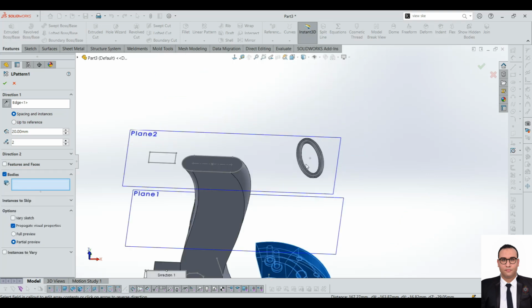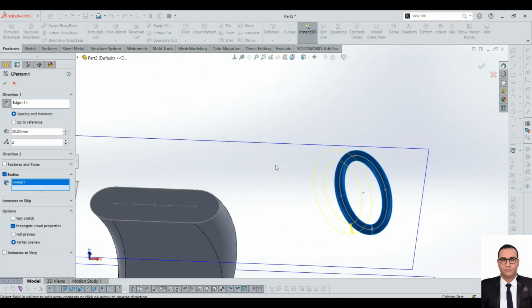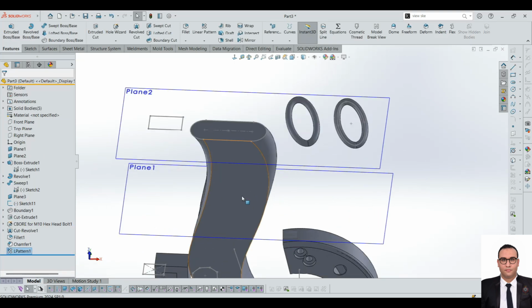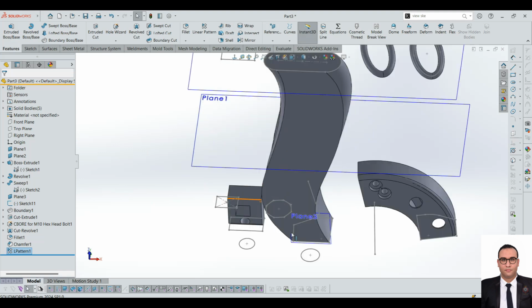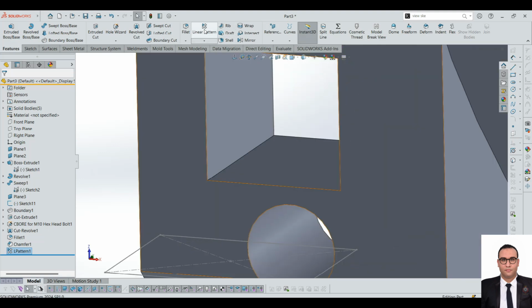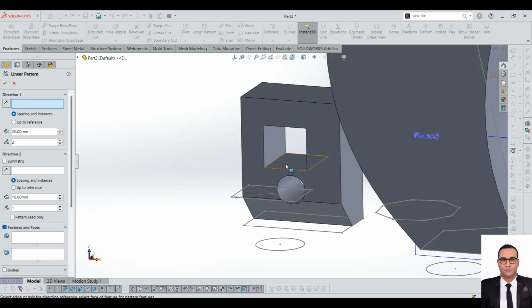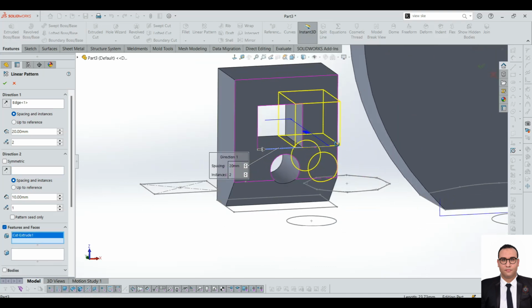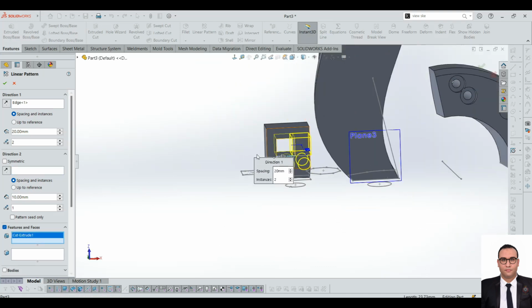If we select this body here, it allows us to do another copy of that body, like this, as you see, or a feature. If we have any feature we would like, as this feature here, we go to the linear pattern, select a direction, any direction we want, and we select the feature here, and it will be done as in the preview. See,